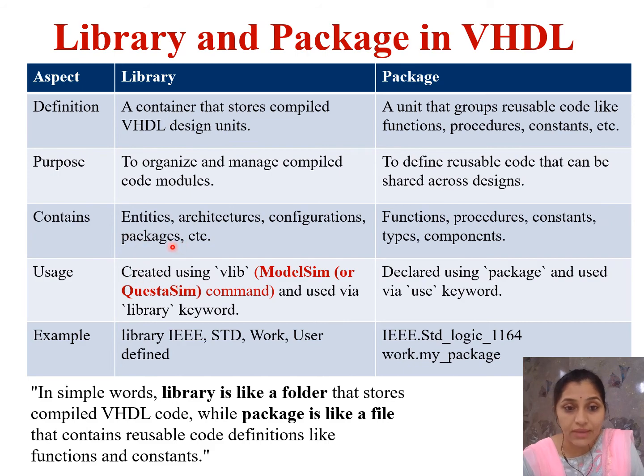Then the library contains entities, architectures, configurations, packages, etc. Whereas a package contains functions and procedures, which are subprograms. If functions and procedures are subprograms, we can reuse them again and again. To store constants, types, components, functions or procedures, we use a package.